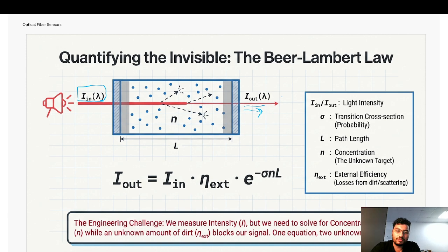moves to the detector. Suppose here is the detector and this is the light, a laser, or for this case maybe I'll write the lamp, which has a particular specific wavelength of light coming in, interacting with the gas in a chamber, and the path length is also mentioned here, how much the path length should be, to understand how much we can quantify based on the path length, how much absorption should happen with the concentration of the gas.